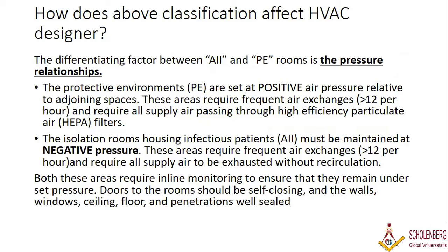These areas require frequent air changes, approximately greater than 12 per hour, and require all supply air to pass through high efficiency particulate filters. That means all outdoor air, which is very energy expensive, with no recirculation.